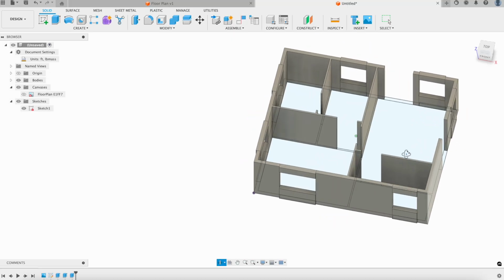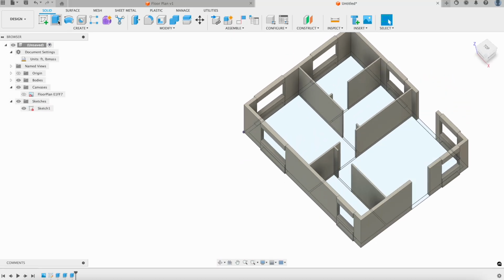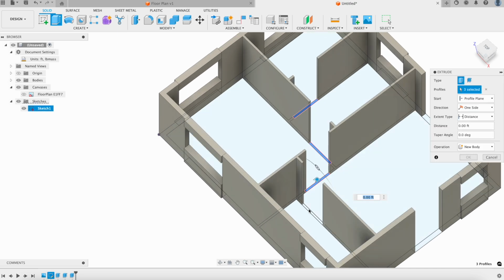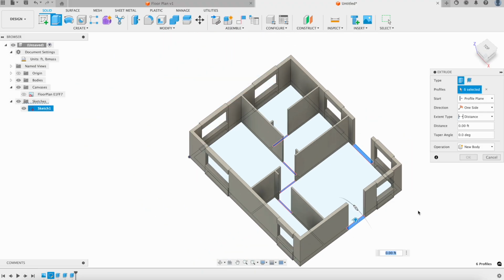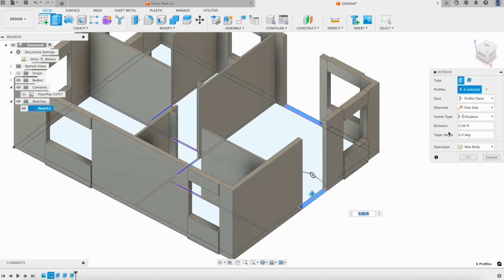And then the last thing that we need to do is just add in those door frames. So what we could do is we could click on everywhere that we see a door. So all of these doors. Okay. And what we could do is we want to also offset that by our door height.